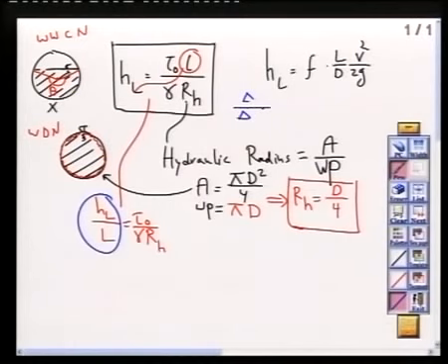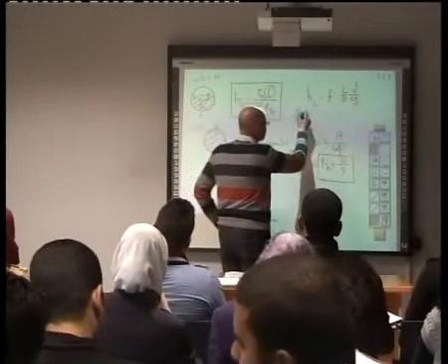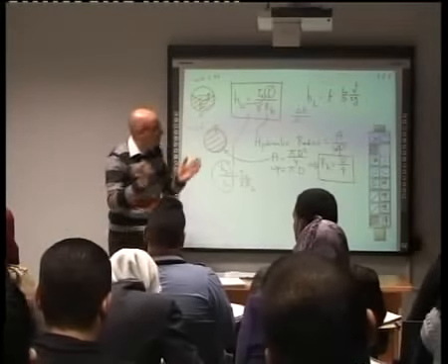But what delta? Is this delta HL? Yes, absolutely. It's a drop in head. So this is delta H. Just quickly recall, H1 equals H2 plus head loss. So head loss would equal H1 minus H2. Simple as that.